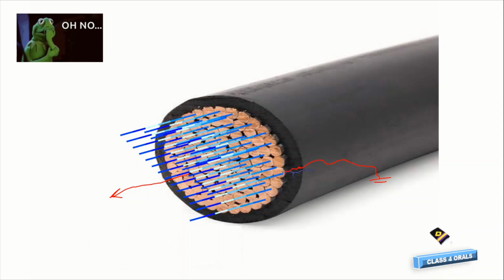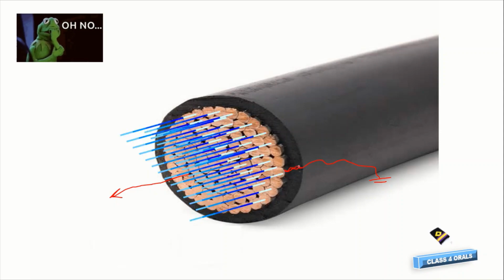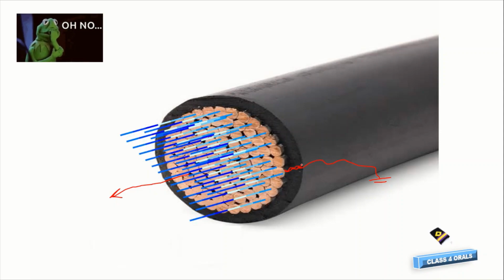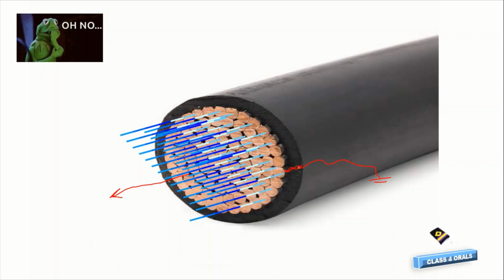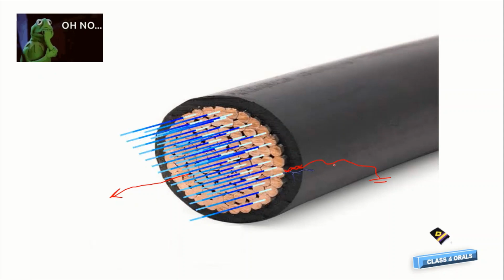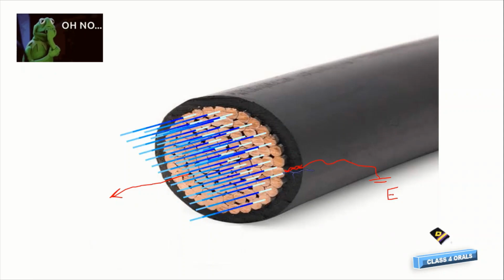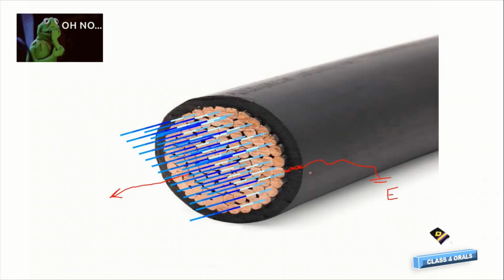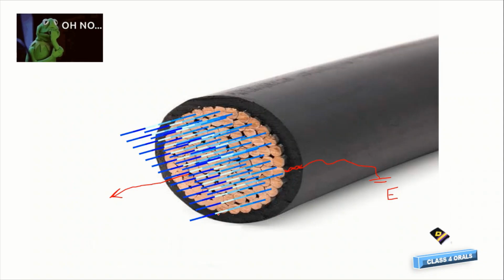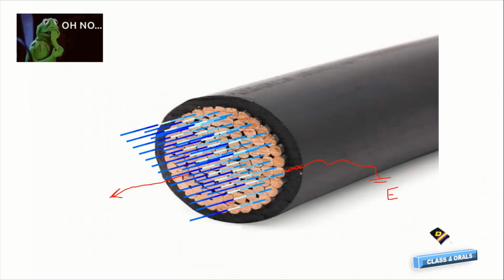You can see that if there is a breakage, leakage or crack in the winding, then the current will leak and find a short path, and it will easily try to go to the earth, which is at low potential. So we are actually going to measure the amount of leakage current. Then we will be able to find the insulation resistance. Okay, so this is how we are going to proceed.